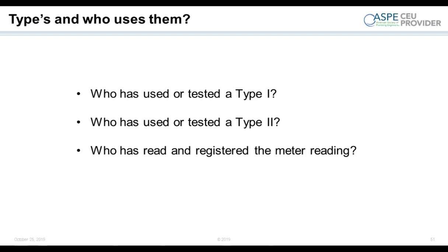Basically they want to account for every gallon of water that comes through, because they want to know, is it people stealing water? Is it leakage? Do they have to start looking for leaks in their water mains? They have to start looking for unauthorized connections. Those meters are there for a reason. People should be recording them.